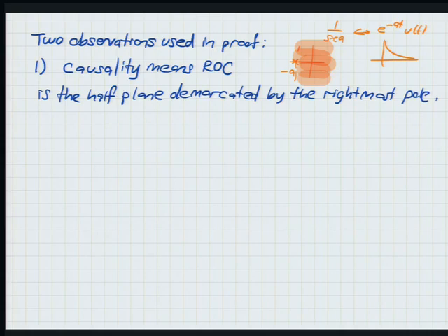Take it as a fact, because I decided not to do a big deal of regions of convergence, but it turns out that under the rationality assumption I made, we're going to have poles, and then the ROC, since h of t is right-sided, will exclude all the poles, and the rightmost pole will be on the boundary. Okay? So that's one observation about causality and ROC. So given that we assume causality, then we'll talk about ROCs that are to the right of the rightmost pole.